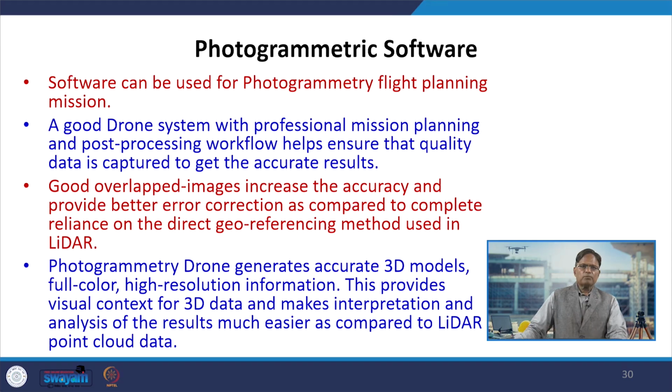All these photos join together to form a mosaic of the whole flight area you can see, and maybe you can drape this area onto a DSM to produce an orthophoto, and this orthophoto can directly be used like a map. So, we will take the help of software.